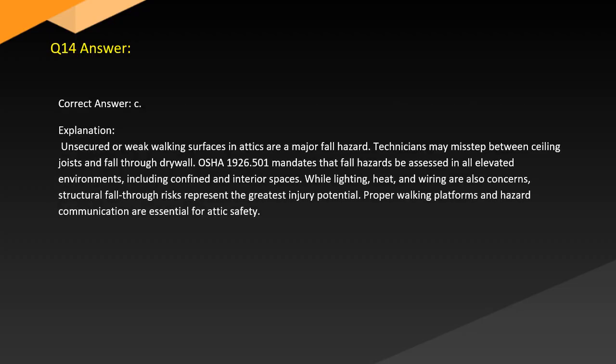Answer. Correct answer: C. Explanation: Unsecured or weak walking surfaces in attics are a major fall hazard. Technicians may misstep between ceiling joists and fall through drywall. OSHA